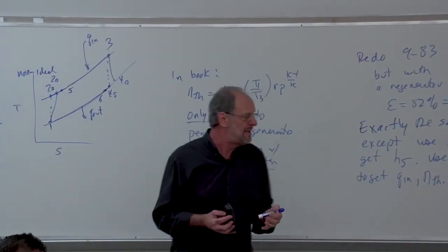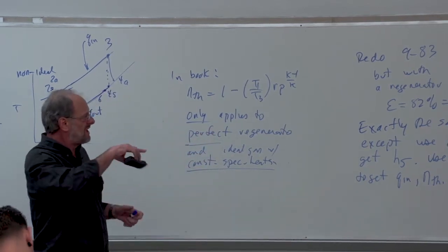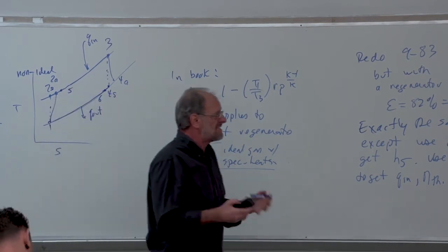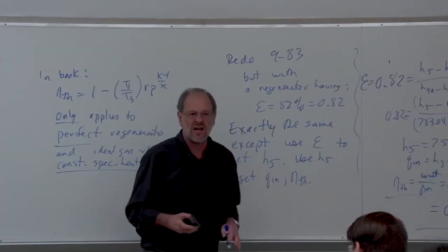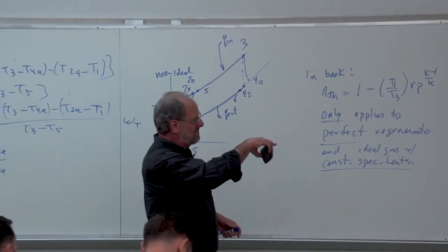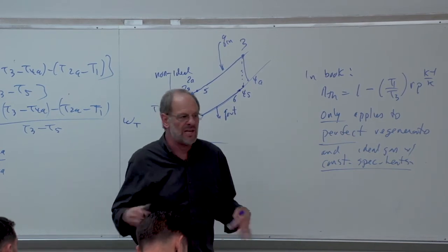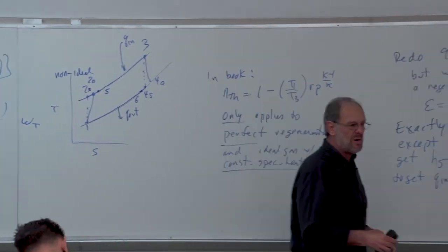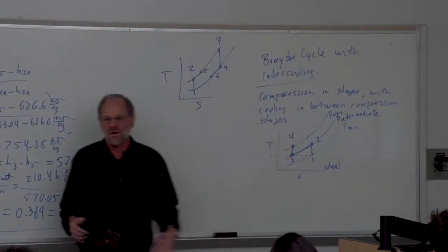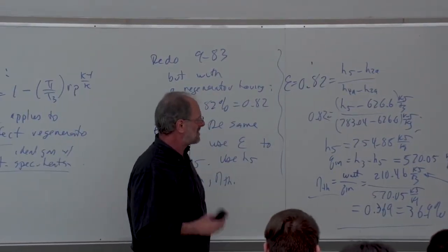Now, in reality, that's not going to be the most efficient. Certainly, if we continue to add compression stages with additional intercoolers, that's going to make it most efficient, but it's just not cost effective. In fact, what I found is that even if you try to add a second intercooler with another compressor, then already it's not going to be cost effective, because this all costs money, right? Yeah, we're going to improve the thermodynamic efficiency and therefore help maximize the power output or minimize the heat input. So that's certainly going to be our benefit.